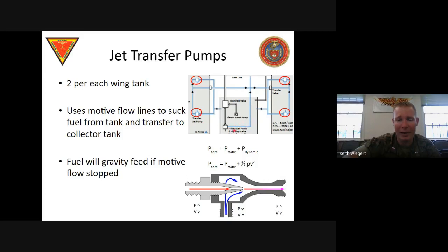from the collector tank, and that's what's gonna, again, kind of make its own little circle with the high pressure fuel pump up there. So its own little circulation there. The primary jet pump is gonna always be sucking up fuel and sending it up to the engine-driven low pressure fuel pump. So we're just taking a small amount of fuel to create this circulation going around the aircraft, right? I think that's pretty neat. If that went over your head, don't worry about it too much. It does make the system a little bit more complicated, but you will need to be able to explain this when you brief it to your instructor.